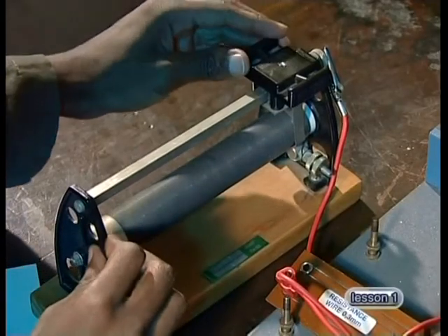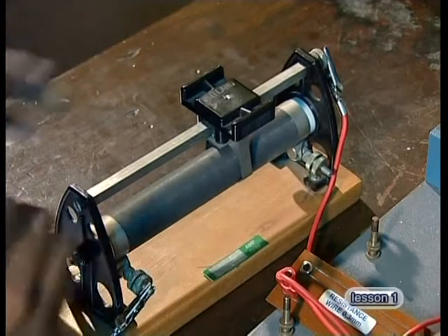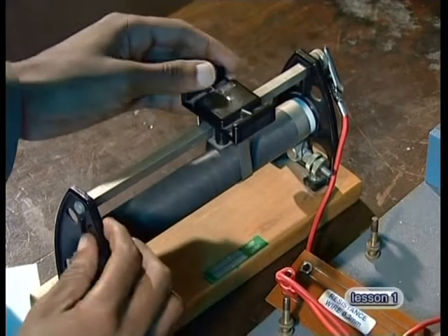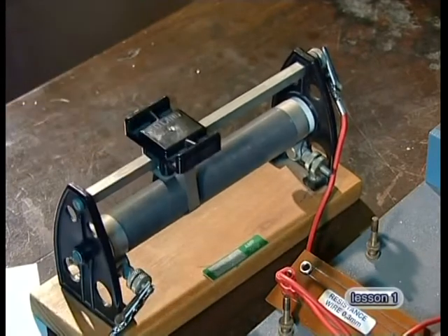Now you'll control the amount of current flowing through your circuit with your rheostat. Because we want to compare the readings on the meters as the current increases, we're going to need to have a small current to start with. So the rheostat needs to be set in a way that the current goes through more loops. By moving the top adjuster, you'll be able to decrease the number of loops and increase the current. I think you're ready to start taking the readings.